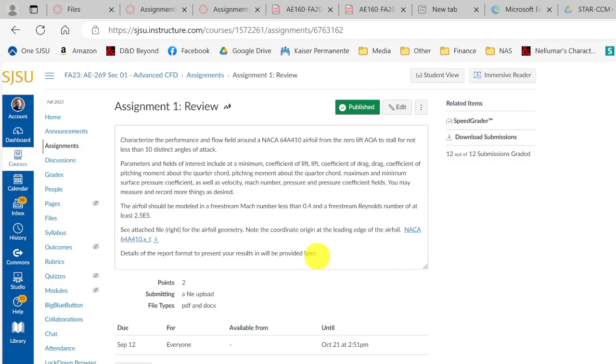The other one was just I need to address the Reynolds number somewhere in the... well, yeah, I don't recall you having particularly mentioned. Also, just as a note, up here, this is a pretty serious discontinuity in prism layer agreement. It agrees much better down here, but I don't expect you to fix it necessarily. Don't worry about rerunning the simulations or anything, just as a point of, if you get a scenario like this, you probably want to have a slightly thinner prism layer. So it might have slightly worse agreement back here, but then it would agree better up there. So I would just make that prism layer a little bit thinner.